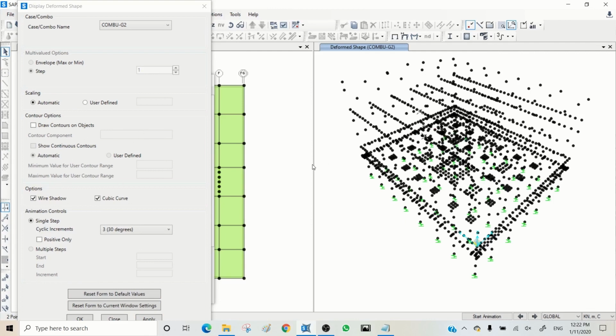So modal analysis doesn't show you all instabilities. Modal analysis shows you them one by one, and if one element is very unstable, you may have a few modes just for that specific element. But when you use loads, then you can easily see how many elements are unstable. You can see a bunch of elements moving here, so it's not just one.